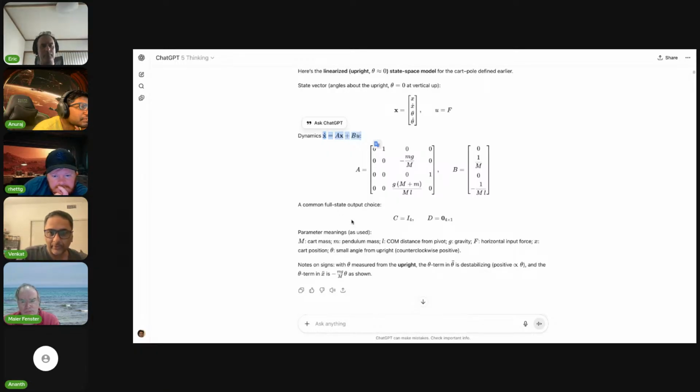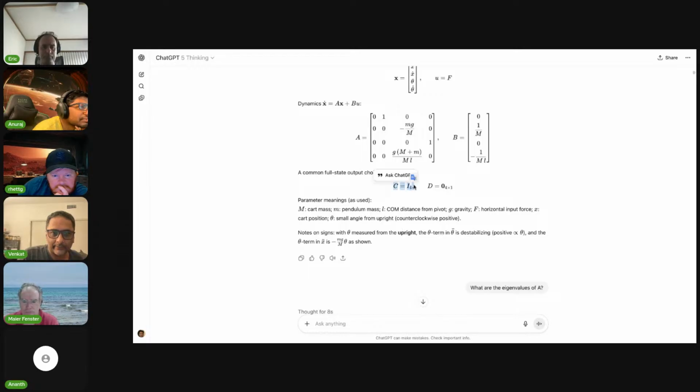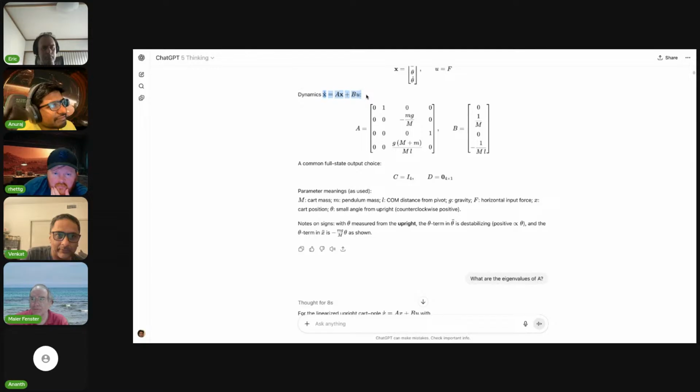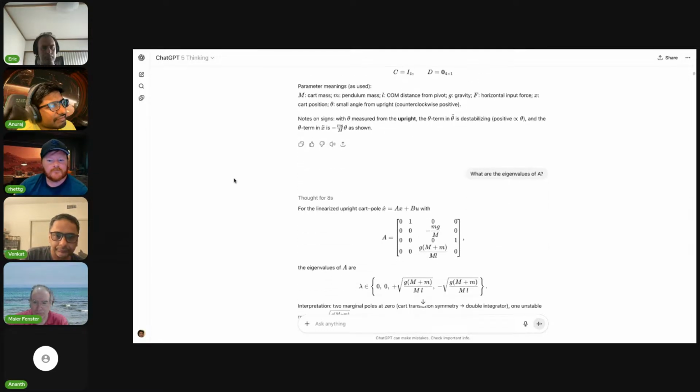And you're assuming that you can observe everything. And the way you capture that is C equal to the identity matrix, which means you can observe all the states. And there's no input passing directly to the output. If that were there, this D matrix would be non-zero. But for any what's known as a causal system, so a cause and effect type system, this has to be 0, because if it's passing right through, it's acausal. So that's the basic setup. If you haven't encountered this stuff before, don't worry about it. If you ever see this equation, this is the basic linear control model of anything, right?